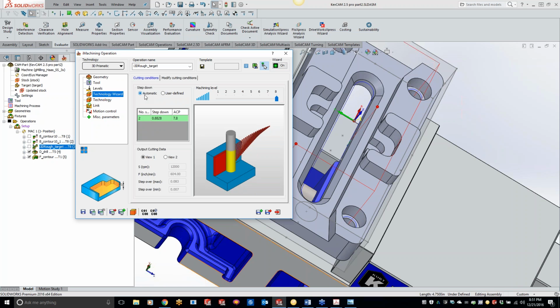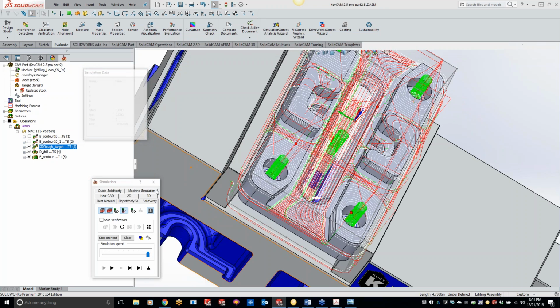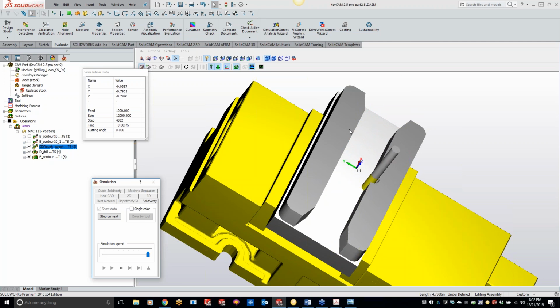Sorry, Kevin, not to interrupt. I apologize, but I was just going to ask: for that chamfer, that's a pretty heavy chamfer around that inside pocket there. Can you say to the chamfer cutter, okay, I only want to take like 100 thou at a time and move that chamfer cutter in? Is that what you're saying? No, this is 3D iMachining. Oh, okay. So if we want to take it in multiple passes, we'll play it through here. Right now it's set to automatic, but maybe instead of doing 2 passes, I want to take 5 passes. And it definitely can do that. Not a problem at all.